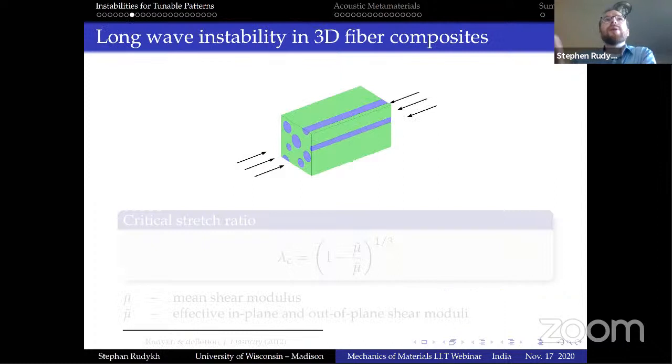Right, so now I'm shifting from a 2D system to 3D, but we're still thinking about a rather similar system. Actually, laminates historically many times we used to make some predictions on 3D fiber composites, and that makes sense as you think about the cross section of this transversely isotropic fiber composite. The cross section will look quite similar to the 2D laminate.